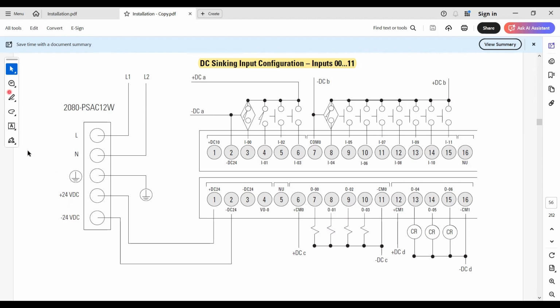It is often confused, like even though this is minus 24 volt and plus 24 volt, the difference should be 48. It is not like that. So this minus 24 volt, even though it is called that, we consider it as ground. So if you measure the voltage difference, it is only 24 volt.